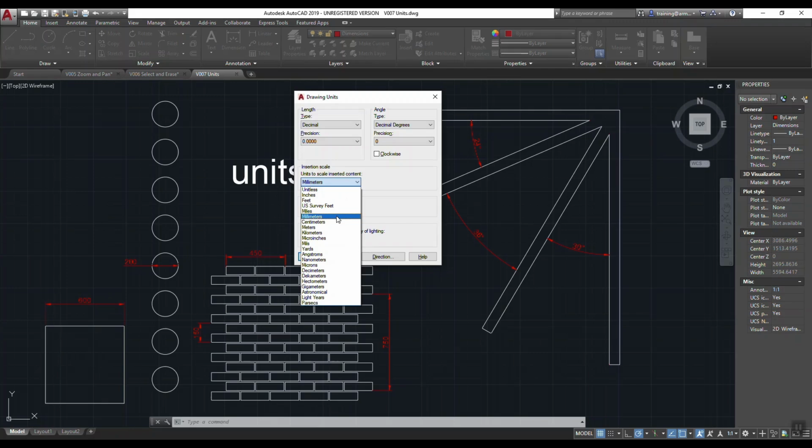So not only does it save space, but it also makes the whole experience faster, because the size of the database is directly proportional to the speed that AutoCAD reads the database. So when you suddenly get a really big drawing, if you've just got it mentioned once at the top, you can fly through the dimensions. But if it was included with the dimensions all the way through, centimeters, centimeters, centimeters, whatever, or light years, all the way through, of course, that's filling up the database and taking space up in your database, which is unnecessary.